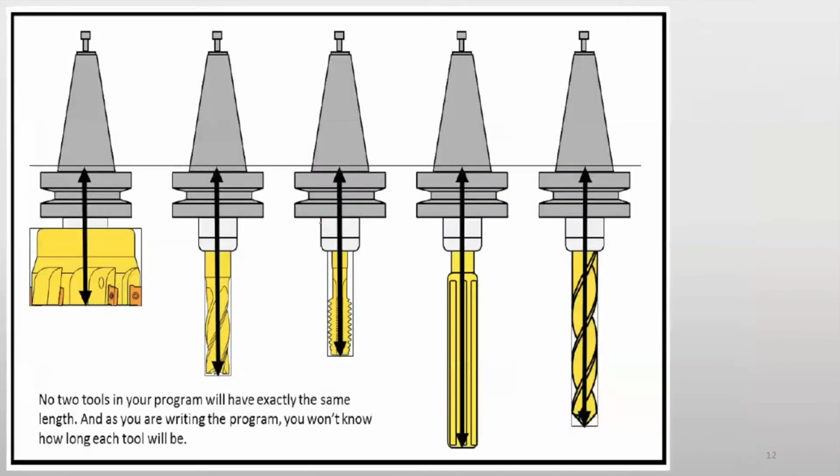And then again, there's another thing I have to do. If you remember the CNC machine, I would be able to put different tooling on it. Each tool has a different height. It's not only height, it also has the thickness, the diameter as well. But let's go with the height. The machine zero is this line, that's where the Z is 0. If I put the face milling tool, it needs to compensate.